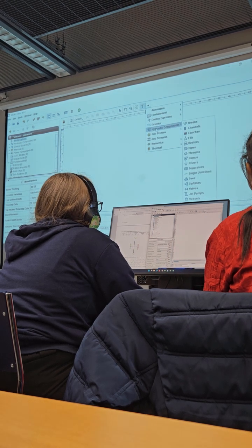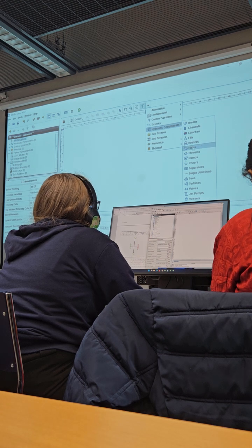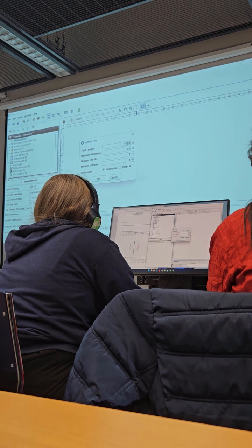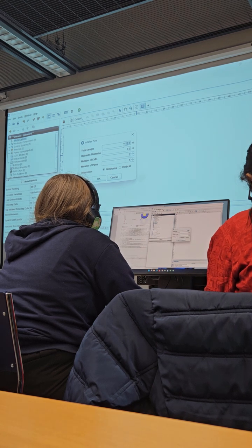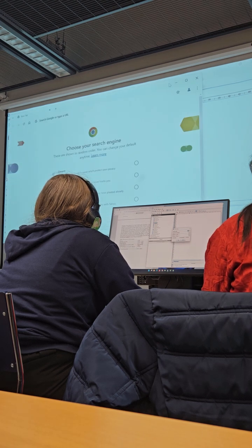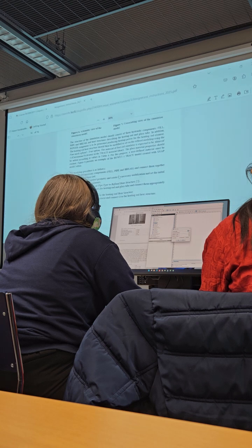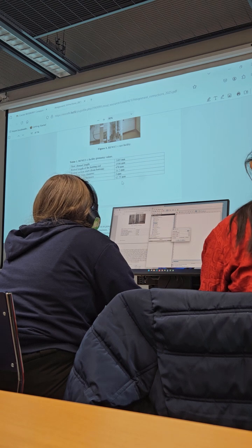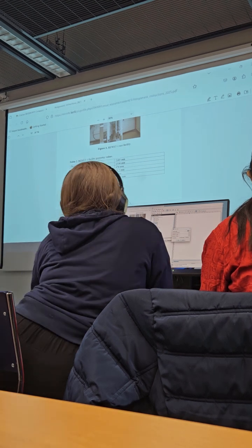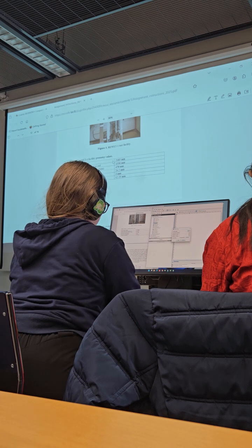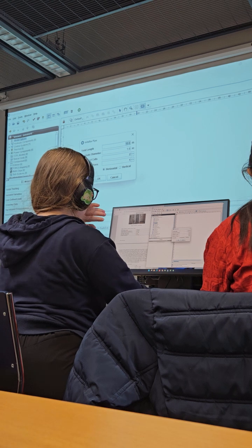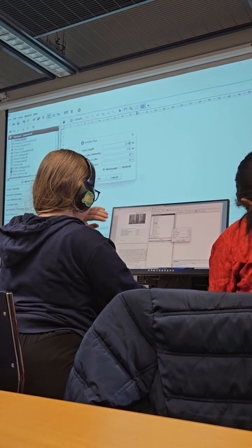So then we need to create a hydraulic component, a pipe. If you click on the field, it will show you the parameters which you can choose. The total length of the pipe is presented in the assignment instructions. There are a few tables with the initial parameters of the coolant, of the glass tube, and the fuel rod. Here we have a flow channel length of 2,185 millimeters. So it is 2 meters 185.